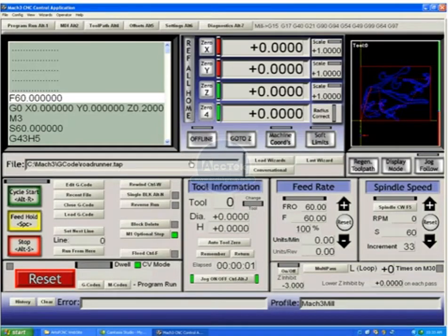Here we'll display the file name that you currently have loaded, and here's a reference button to send all our axes to 0 to our home switch. If we press reference, you'll notice that the y-axis is now moving up, and now it hit its switch, and now the x-axis is moving to its switch, hits it, and then backs off the switch.